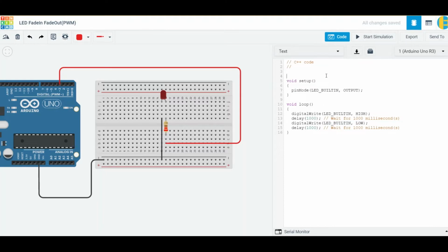We see how our analog signals can be sent to our LEDs. We define here variables for the LED. Because we want to increase the brightness, we want to send the analog signal to increase the brightness of the LED. So we use one variable brightness and one variable fade increment INC for the system.